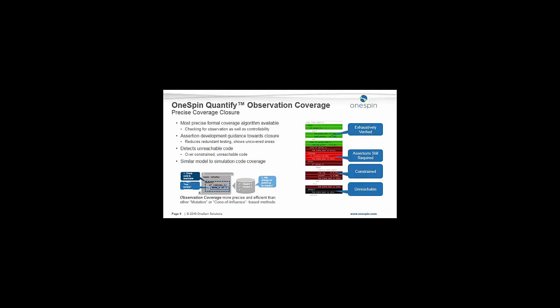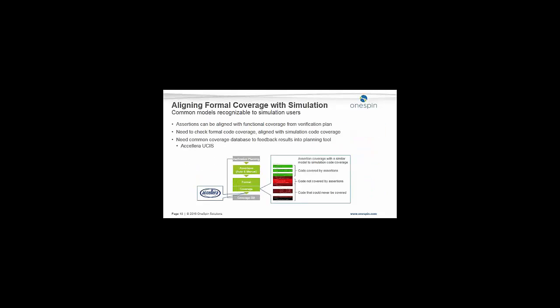And then there is quite an interesting thing here. The brown code means code that is not operational. It's like the black part, unreachable, but due to constraints. That's really valuable information to the verification engineers, because it indicates that there's quite probably some over-constraining taking place. You've put some constraints on your design that stop this code from ever being executed. So why did the designer write it in the system if it doesn't serve any purpose? That normally shows there's over-constraining, which can hide bugs. So it's all really quite useful.